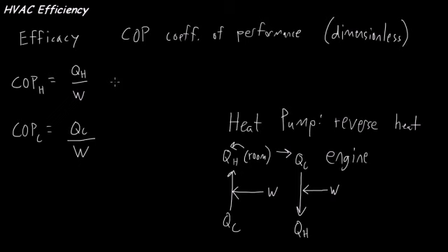For example, if I have a heat pump and I can place heat equal to about 4 kilowatt hours for every kilowatt hour I supply to the compressor, then it would have a COP of 4. Usually for equipment there's a single number given for COP. Sometimes there's a single number, but it actually varies with temperature. Heat pumps have a certain temperature range that they like to function in, and if they get below that range, they don't work very well.